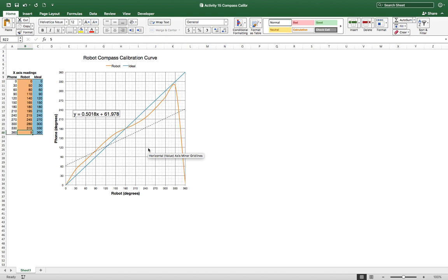We can set that to 360, and we have a more realistic equation then, as opposed to something that is really drastically off. So just some pointers. This is a really interesting part of the activity. You're going to want to calibrate your sensor and then also find an equation to even further remove that error for your compasses especially.